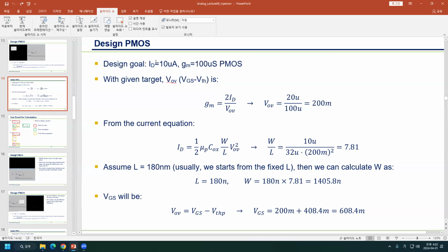For example, let's say this amplifier has a really tough noise constraint. That can happen when you design an amplifier, because of the application, the noise of this amplifier should be really low. In that case, usually what we do is choose a large L. So it really depends on your application. If you don't care about noise at all, then we're not going to use a large L.